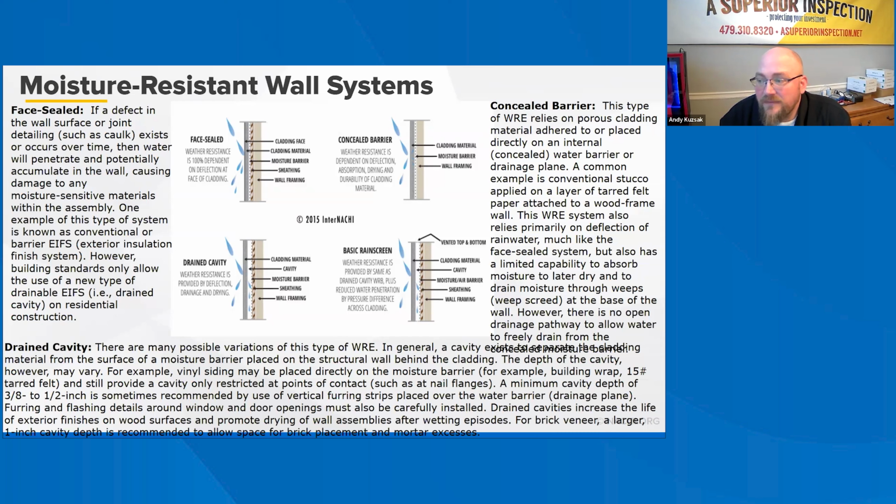The exterior wall envelope shall be designed and constructed in such a manner as to prevent the accumulation of water within the wall assembly by providing a water-resistant barrier behind the exterior veneer as required by section 703.2 and a means of draining water that enters the assembly to the exterior. Protection against condensation in the exterior wall assembly shall be provided. There are some exceptions.